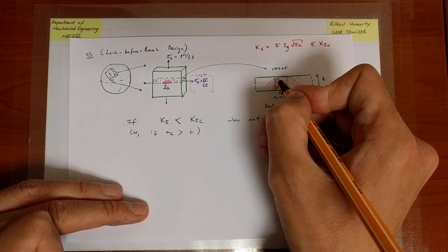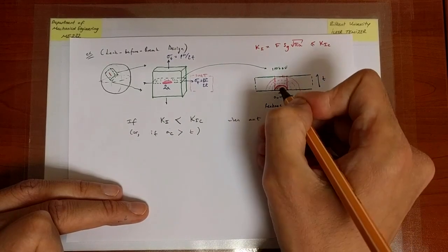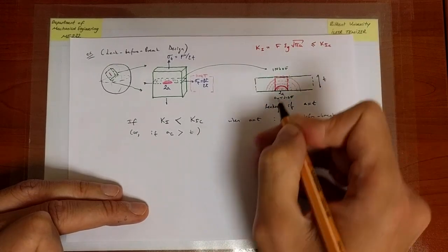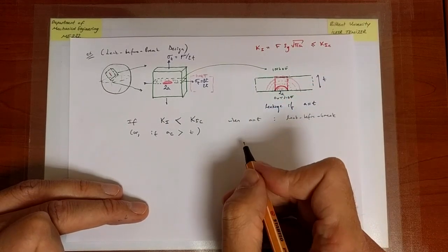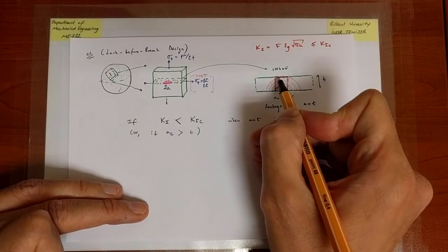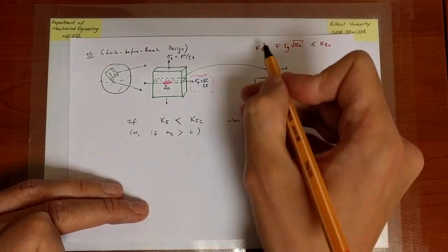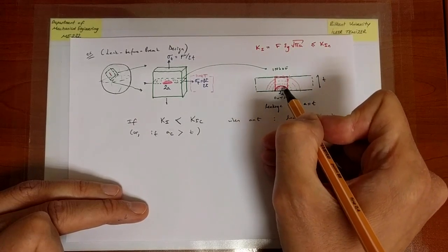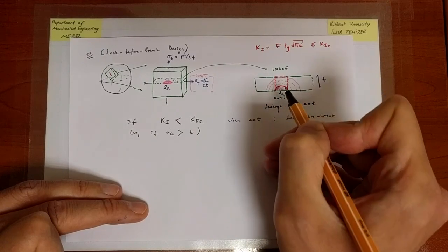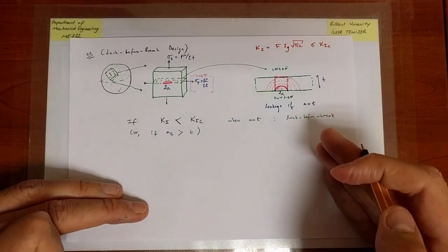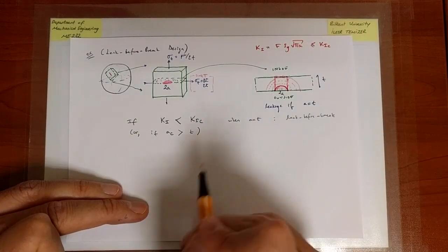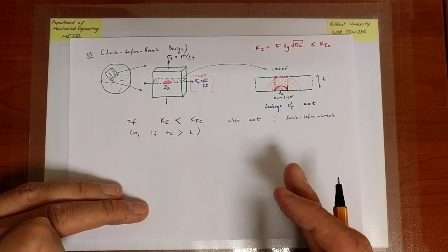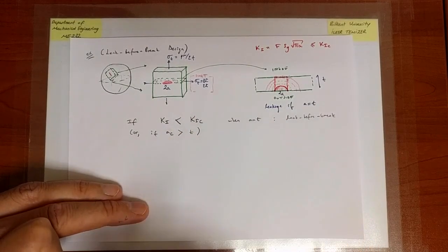But what I'm going to do is I'm going to assume that the crack is not of this size, even when it's penny-shaped and like this, but actually of that size, okay? So I'm going to assume it's larger, and hence the value of K1 that I will calculate, because the crack size is now assumed to be larger, will be larger than the K1 value corresponding to the physical penny-shaped crack, and hence I'm predicting K1 to be larger than it is, and I'm comparing it against K1C. So I'm going to be conservative. So I'm going to be safer. Now, I might be too conservative. I don't want to be too conservative, but at least in the context of this example,